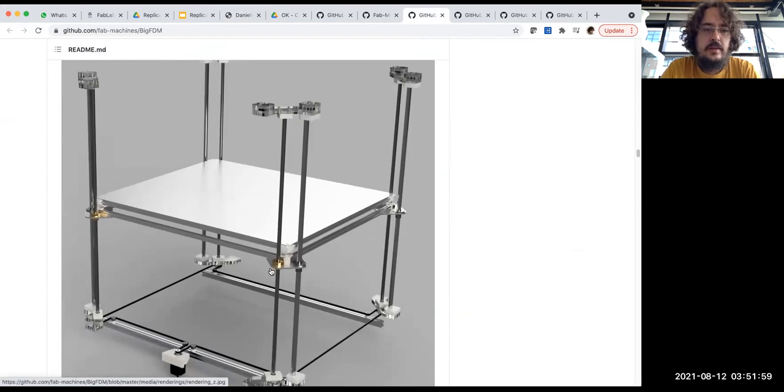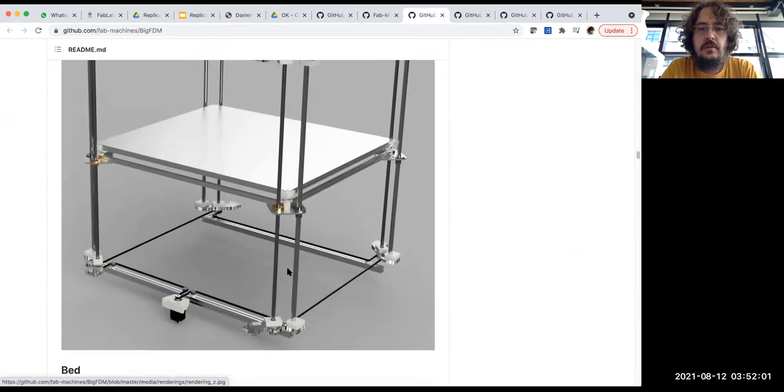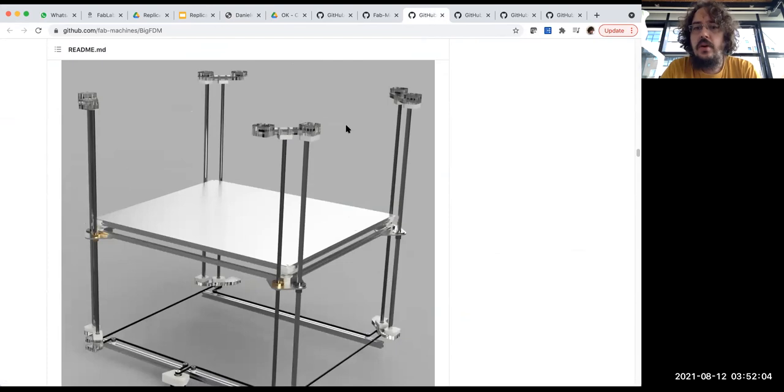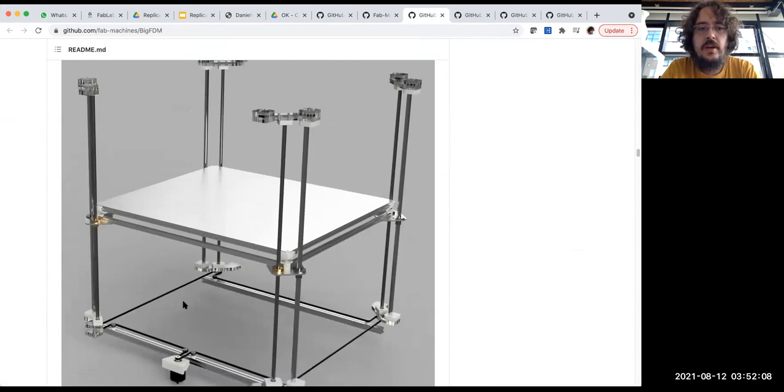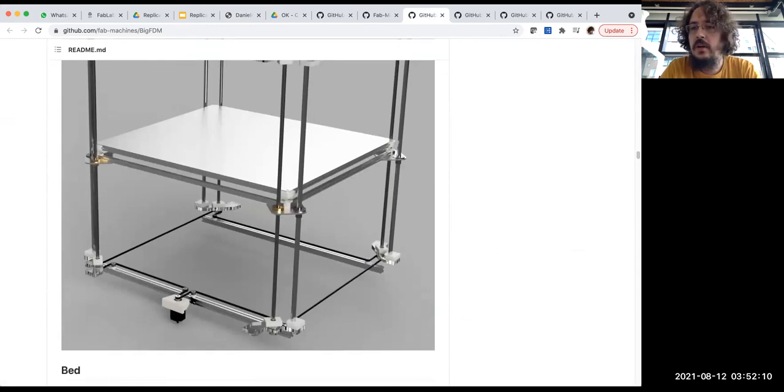To operate this motion, I needed 4 lead screws, 4 linear shafts, 4 linear bearings, 4 platforms on the side, plus a very complex system on the bottom with a closed loop bed. I could also have 4 motors, but then this would mean 4 drivers or more powerful drivers, and the motors should be synchronized as well. So there are even more complex systems than that.